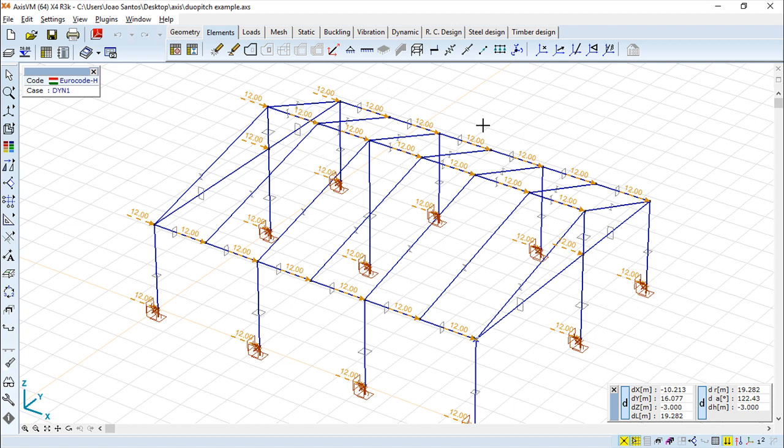Second step, we need to determine the load transfer path. Third, determine load discontinuities such as stiffeners, gussets, holes. This is a little about the modeling of what we want to calculate and the structure we want to simulate.